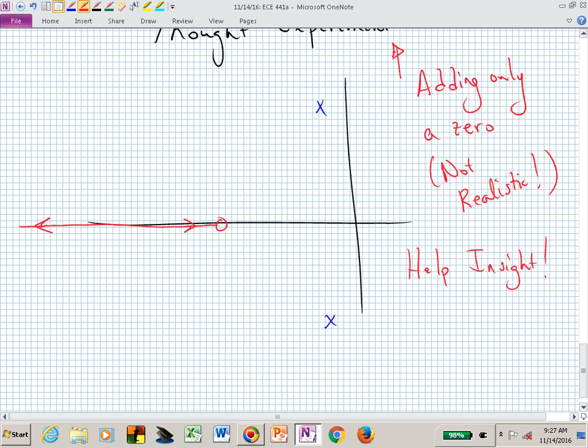So it doesn't really matter. Let's just do this. We're just thinking, but they have to somehow come to the real line. One branch will go to the right, one will go to the left. And they meet where? If you needed to find that point, how would you find it? Where they come into the real line. Trying to not say the word, but they're re-entering the real line. That's a re-entry point. That would be a relative minimum of your gain value from the magnitude condition. Another way to use some of these rules.